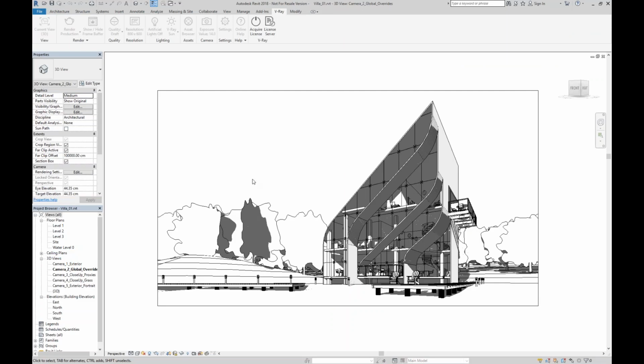As I mentioned, V-Ray for Revit installs as a ribbon part of the Revit environment. Initially, the toolbar buttons are grayed out. All you need to do is click the Acquire License button to turn on the toolbar and make it active. Your V-Ray for Revit license is not engaged automatically when Revit is launched. This is very useful in many cases.